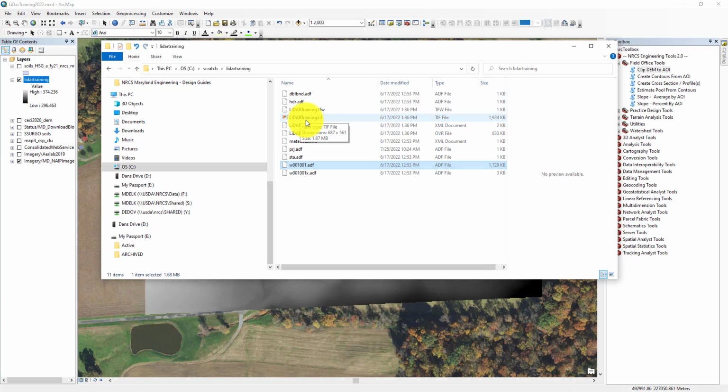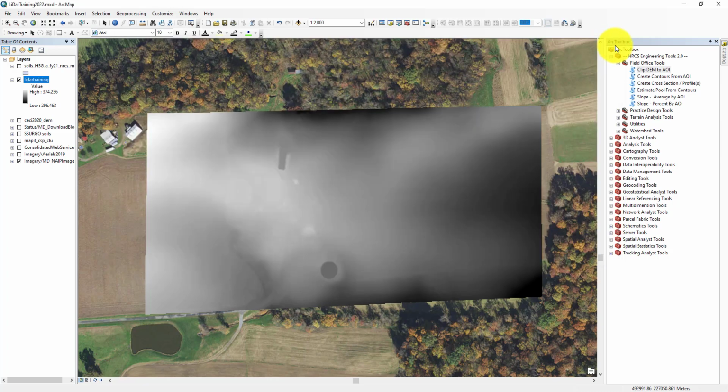And if you were to do all your work and submit that in, it's going to give you an error in Civil 3D saying, well, this is located under this person's name in the C scratch folder or workspace, whichever folder you created. So you have to make sure that you bring this data into your engineering working folder when you upload it.